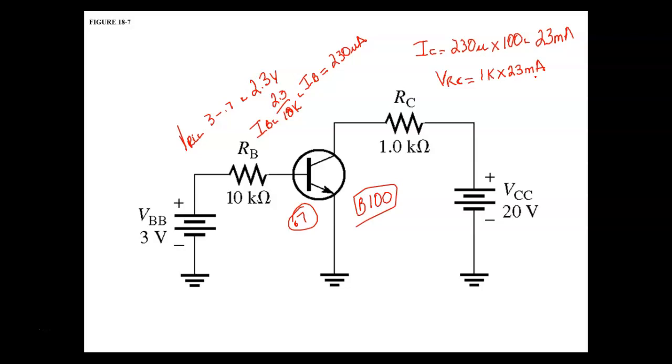You're exactly right. So you can't drop more than is applied, right? You understand that. So this guy's going to drop 20 volts or around there. So how much is the transistor going to drop? 0. So it's saturated. We saturated this one.